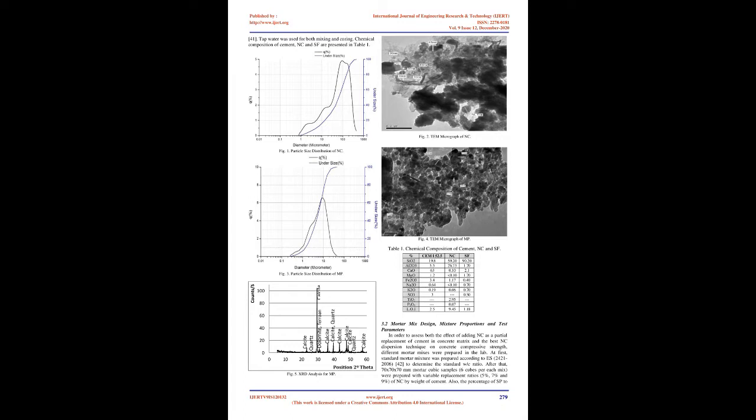Saaid et al. 35 reported that introducing the required mixing water by sprinkling technique, which is simple and applicable, was more effective in enhancing concrete properties compared to traditional technique, pouring the required mixing water directly into mixer. Moreover, using sprinkling technique reduced the mixing water content while maintaining the mechanical and physical properties of concrete at their ultimate levels. Natarajan et al. 36 investigated utilizing different amounts of MP and green sand as fine aggregate hybrid replacement, besides, constant percentage, 5%, of metakaolin as cement replacement, by weight, on the strength and durability of concrete.